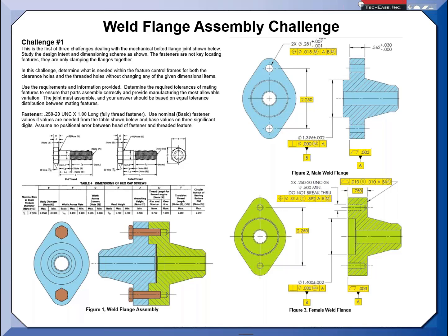So what winds up happening, we have a term for that. What we call that is a non-rigid part, when you're dealing with plastics, or parts that may not hold their shape due to either their size or variation. We call those non-rigid, and it's very typical. I mean, sheet metal, if I'm bending up a sheet metal piece, you get spring back. We do have controls, believe it or not, to meet the requirements. So on those types of parts, dealing with the flatness, there's a couple things you can do.